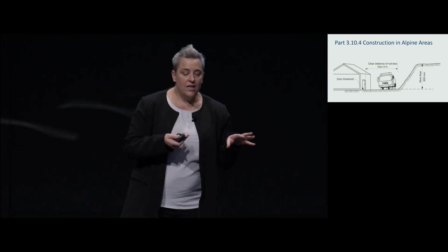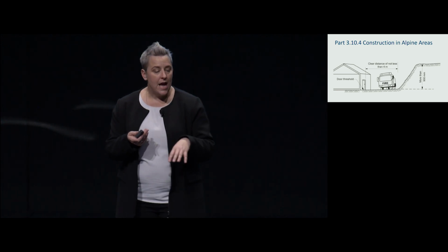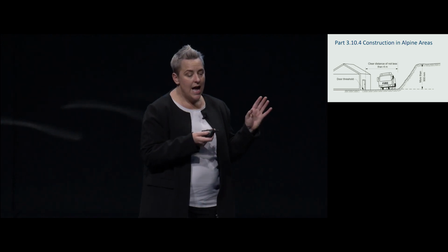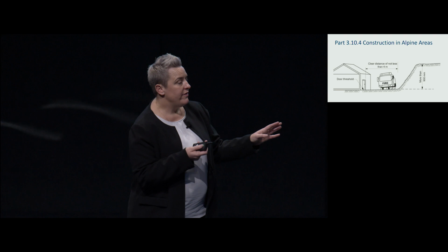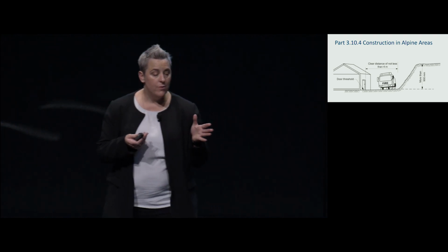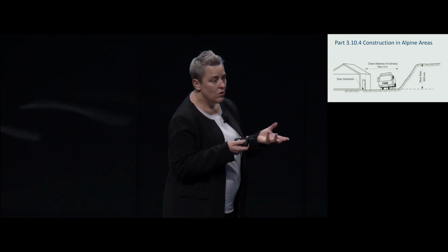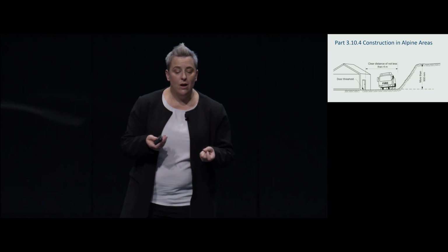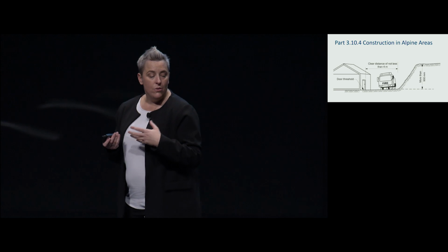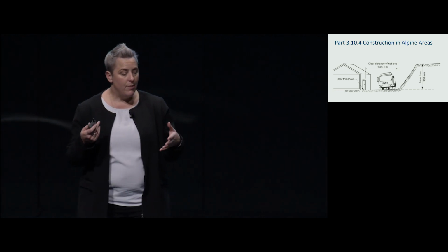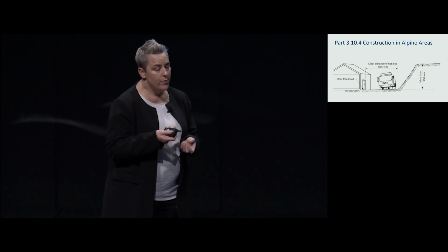The requirements for the external doors have been amended, and you are now permitted to include a sliding door, when previously you could only have a door that opened inwards. There's also new requirements for the threshold to be not less than 900 mil above the adjacent surface, which is to ensure that your snow build-up won't prevent the door from opening.